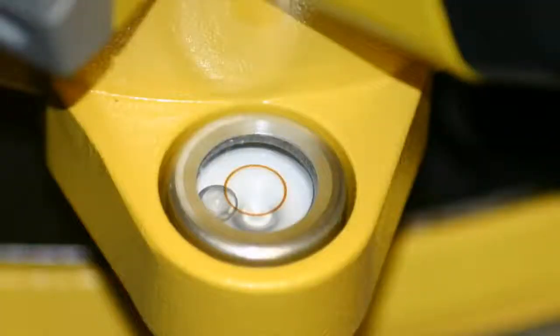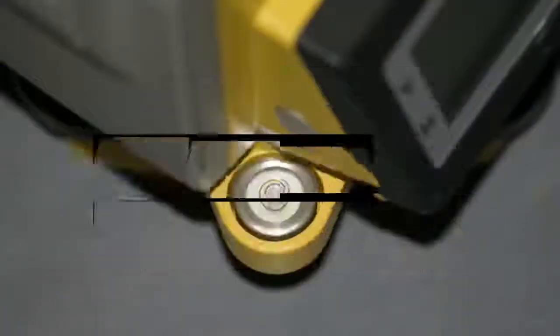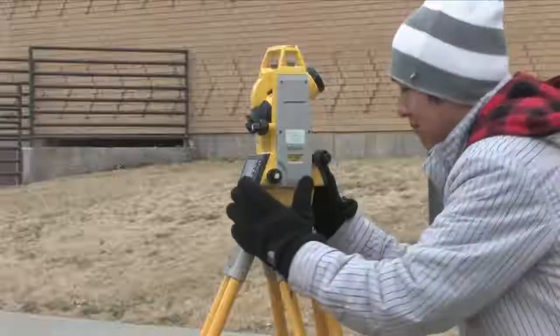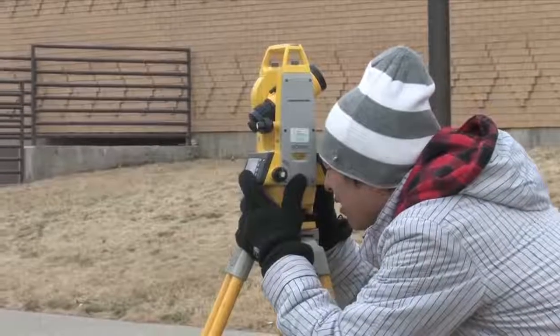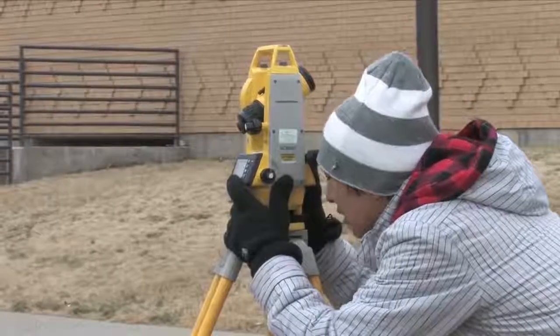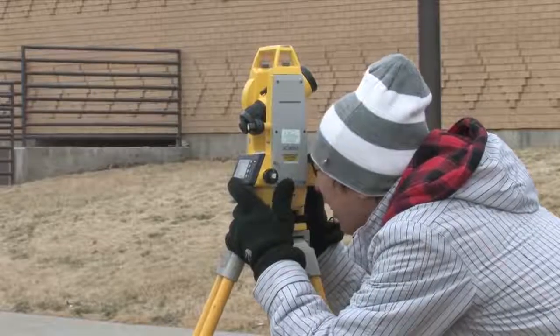Next, ensure the instrument is level by adjusting the 3 leveling screws on the tribrach at the base of the theodolite. Ensure that the bubble is at the center of the circle on the level. To verify that the vertical axis of the digital theodolite lines up perpendicularly to the center of the traverse cap, use the optical plummet located at the side of the instrument to look through and verify that the circular rings are on the center of the circular traverse cap.